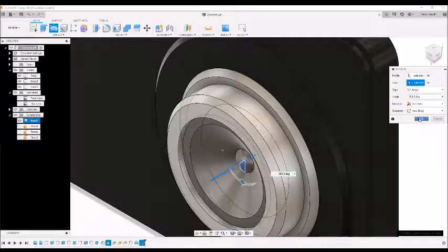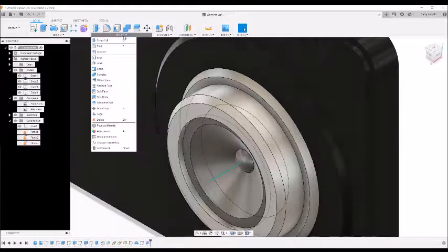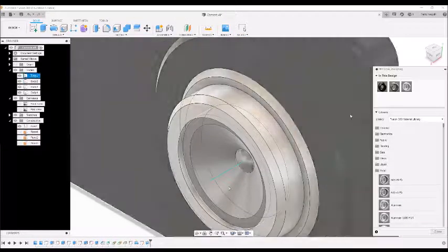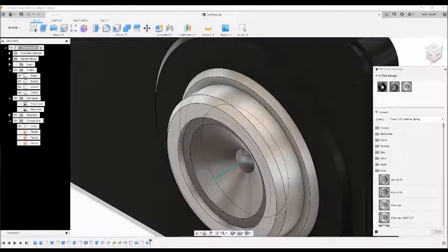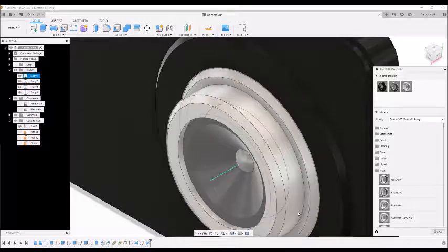So once I've used the revolve tool to create a new body, I can now just use the materials tool to give the inside casing a black plastic finish like on my original image, and I'm just going to use a glass finish for the lens.